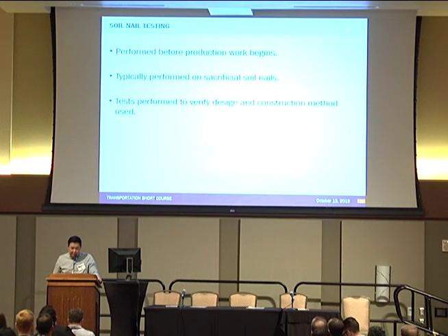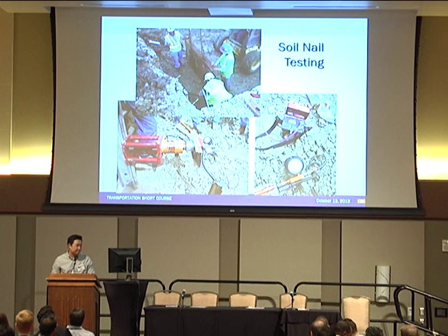Sometimes the contractor is allowed to proceed with construction without soil nail testing at their own risk. It is a somewhat risky approach, so typically we recommend running soil nail testing before the production nail installation.